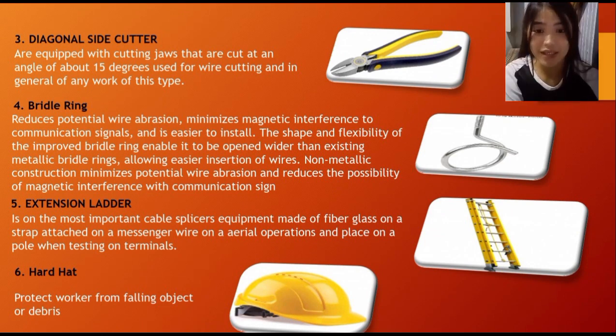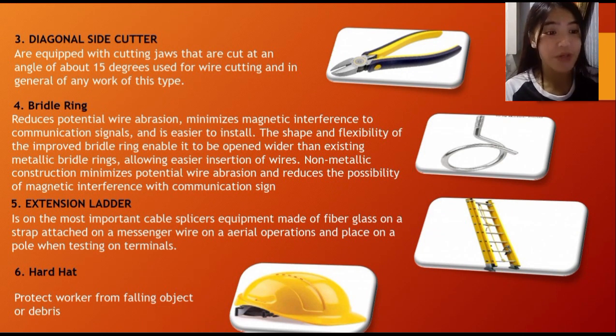Next one is extension ladder. It is one of the most important cable splicers' equipment, made of fiberglass, with a strap attached to a messenger wire for aerial operations in place on the pole when testing on terminals. So the next one is hard hat. It protects workers from falling objects or debris.